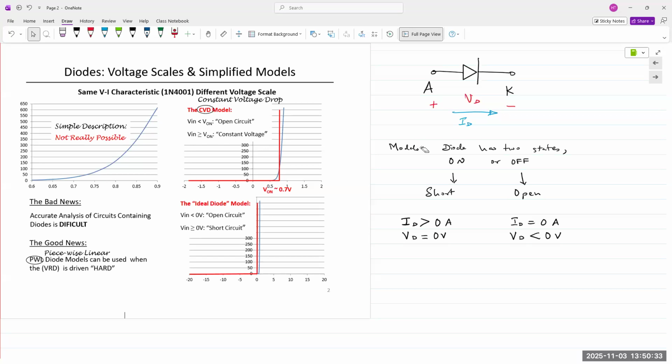So the question being asked is, if I understand correctly, does it have any resistance? No, the diode will not have any resistance in that case. Hence the term ideal diode and constant voltage drop. So it's a very good question, since we said that real life diodes have a model of a diode in series with a resistor, which is RS. In this case, RS would be equal to 0. Absolutely no resistance in the pathway.